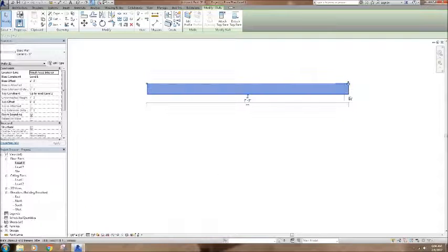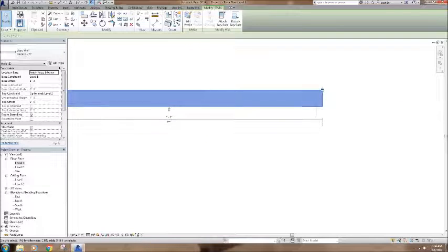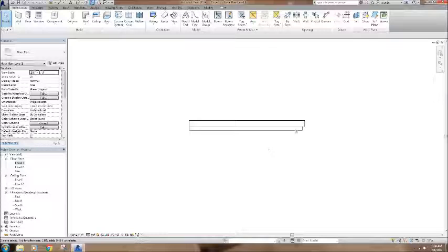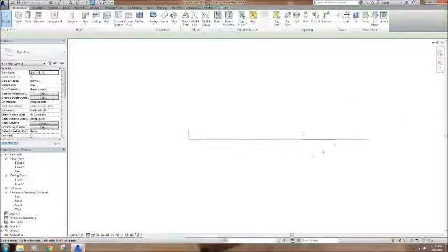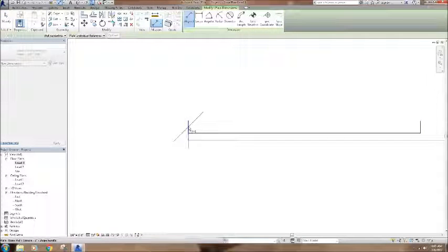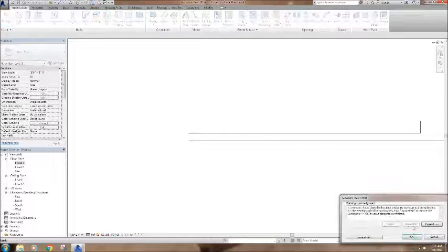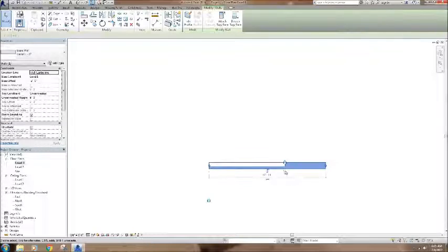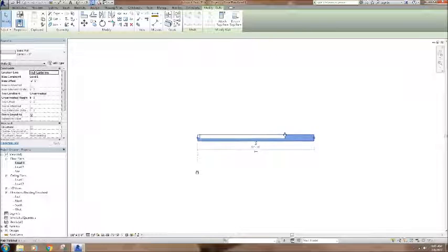You could also put a lock on the end if you wanted to keep it in line at the very end here, if that was a condition that you were concerned about. So if I drag this down here, but I always want this one to stay in line, I could grab the end here and grab the end here and put a lock on that as well, and then get rid of that and say OK. And now if I shove stuff left and right and back and forth, it keeps this always where it is, and then also the other direction.